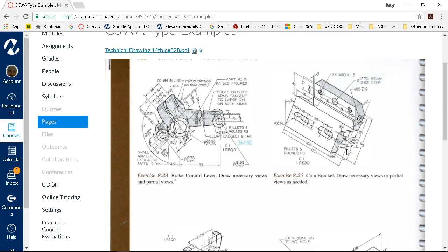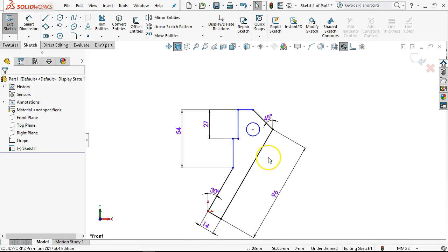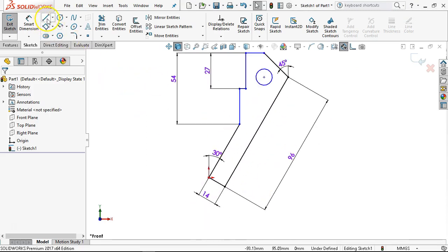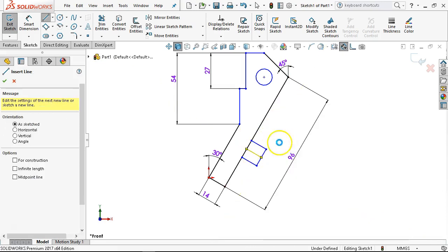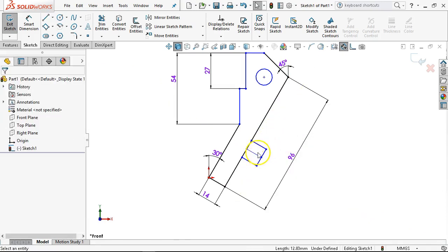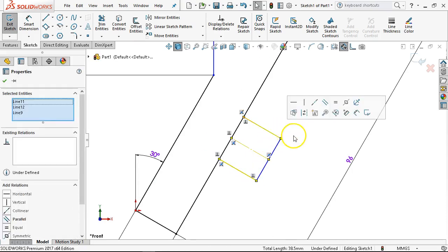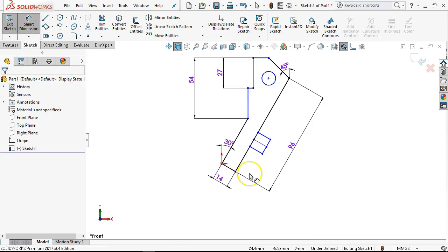So 5 millimeters on the depth, 51 up, back from the point. I'm not concerned about the 30 degree. And hopefully we will, well, we'll just have to stack up until we see an overall. Alright, so a couple of lines. And then we'll go from the midpoint back so that I can leave those symmetrical. That needs to be a construction line. Oh, let's see, I got midpoint, so that one's already in there.